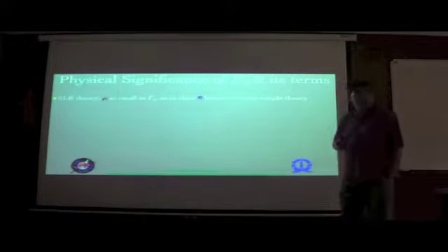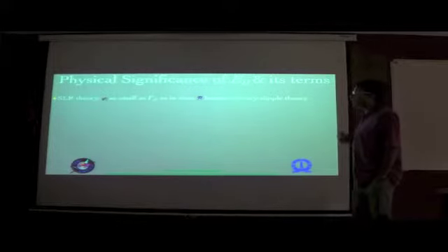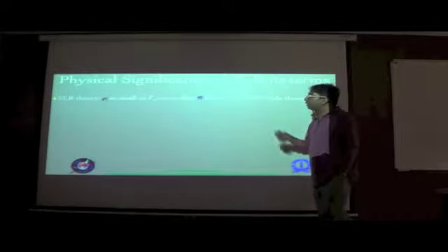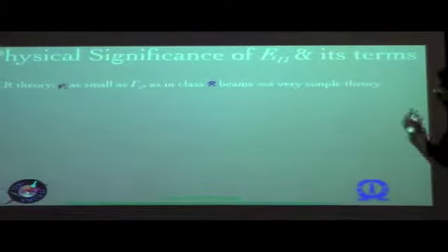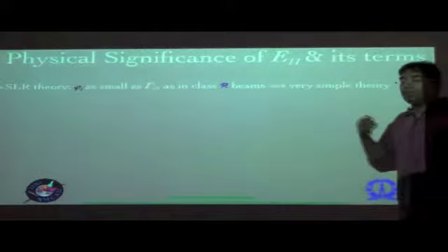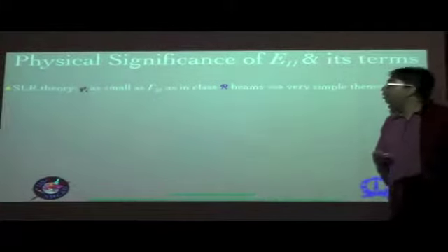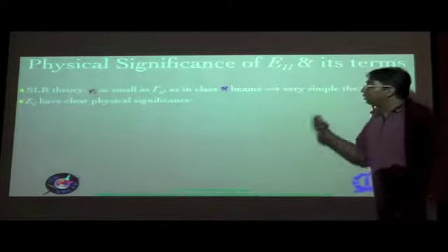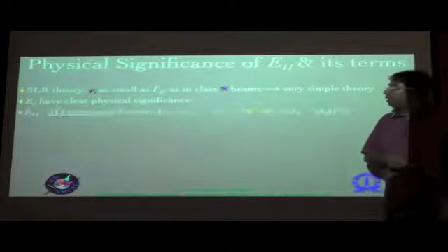Again, we had 2 aspects to it, the small local rotation theory and the moderate local rotation theory. For the class R beams, the local rotations were small, so we had a very simple theory which just gave the 3D strains as the symmetric part of the deformation gradient matrix minus the identity, which is what E is defined as.